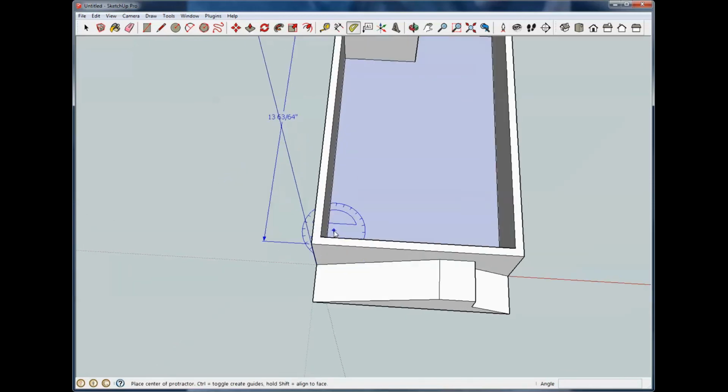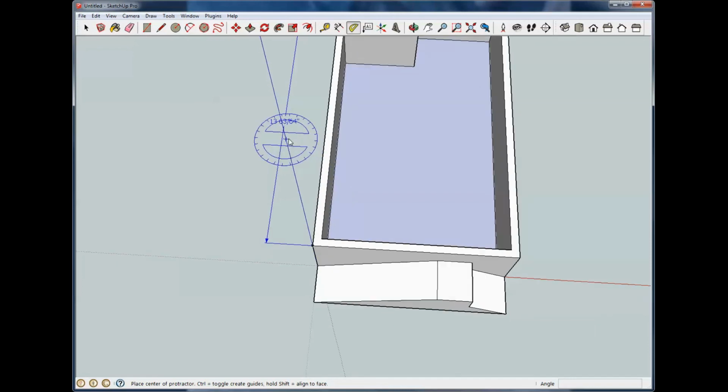So if we wanted to come up here and wanted to draw a guide across here 45 degrees or measure something, we could go down here on this. We're on our blue axis, what we want. Come up here, set our reference point, and we can swing around and notice how this will snap to the end. If you look at the angle down there on the bottom right, it says that it's 90 degrees. As we move in between, it shows the various angles. If we wanted 48.1 degrees, we just type in 48.1 and we'll end up with a guide that's 48.1 degrees.